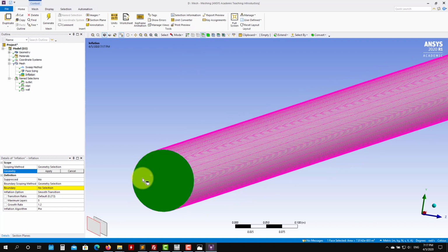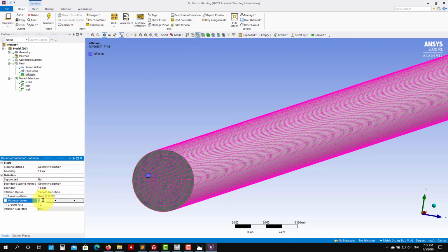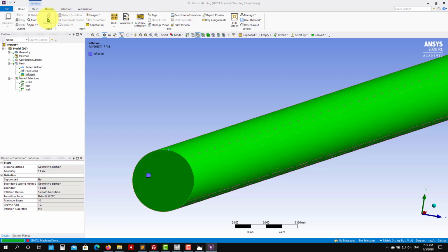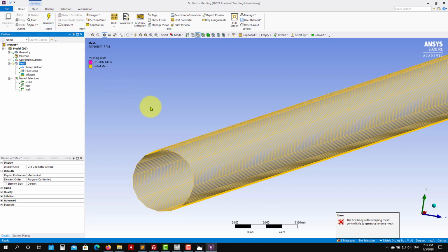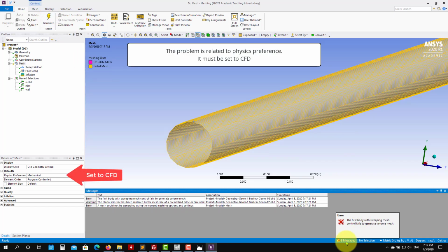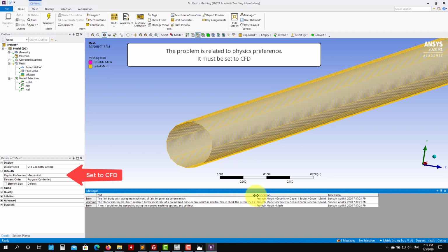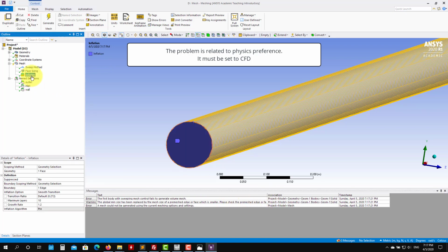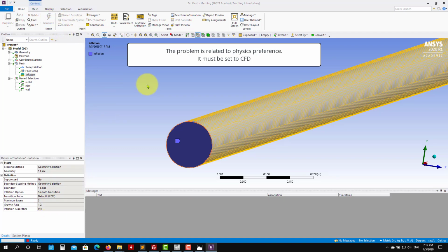So if you do this one manually, your problem here should be fixed. Sorry, it's the face. Boom. See that now you can select it. Select the edge, which is this one, and let's do some 10 layers, and we go there. So remember, if you are using this method, you need to... okay, it's giving me this error about a mesh connect, current actions and setting size, mesh, pre-mesh. Okay, so let me go here, 5. Let me redo it. Probably I need to select the target face as well.